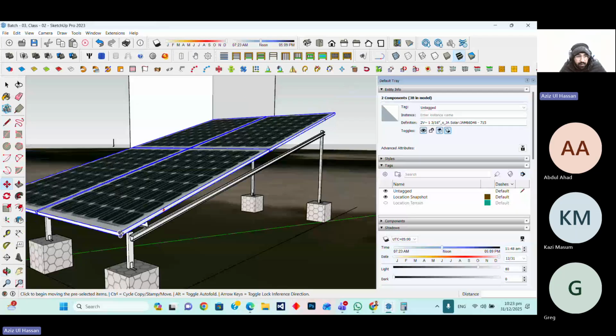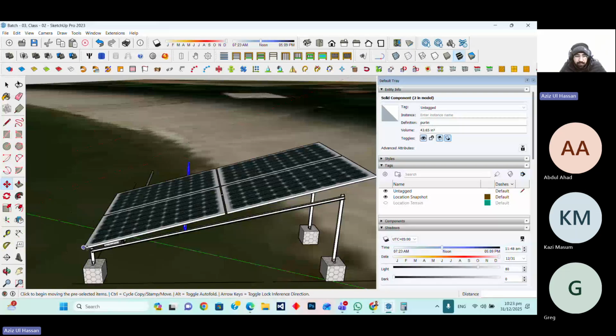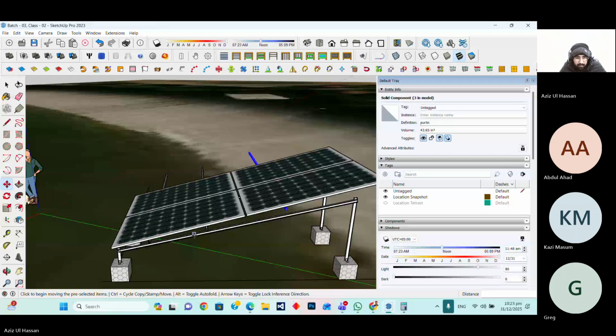These purlins should be as per their installing holes, so around 14 mm distance between the inner installation holes. So I'm just roughly placing that one in that location. So just copy that rafter and place as per their locations.